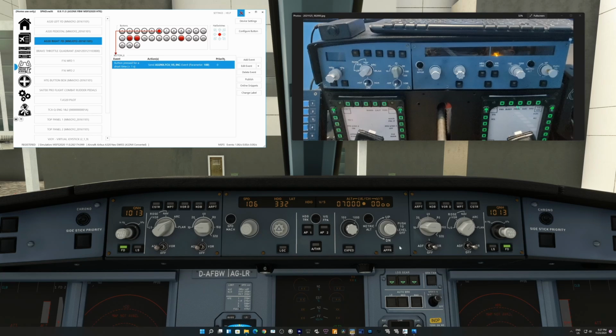On this panel I can also press this one. It's a push button basically. You can see here it's 19, so it becomes Mach, and this is the command toggle, and push again becomes speed knots again. Okay, and this one is heading, track and FPA, or the bird. So basically this is track FPA, and press again, heading mode again, okay, vertical speed.